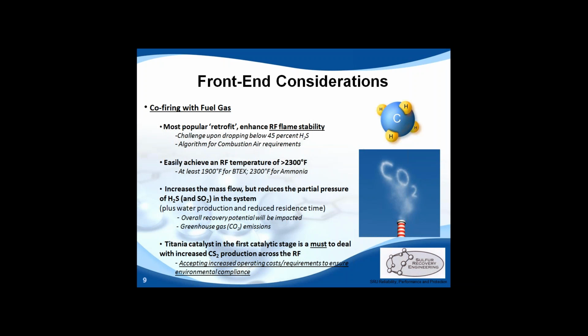I did mention earlier a side reaction in the reaction furnace where hydrocarbons plus H2S can yield CS2, or carbon disulfide. This is sulfur tied up in a form that is not H2S or SO2, and it's those two components that react together at a 2-to-1 ratio to generate our final product, sulfur.